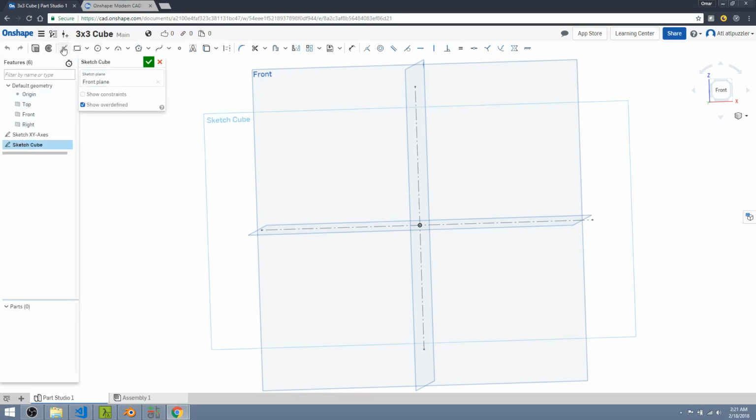Double click on it, and I'm going to choose the rectangle icon here. There's two ways you can draw a rectangle: by corners or by center, and it doesn't matter, either work. In this case, I'm just going to use the center, and hover over the center until the icon looks like this icon here. This basically ensures that the center of your rectangle is the center of the design itself. And just single click and drag and just draw whatever, and single click again, and we have a rectangle. And now click escape so we can stop drawing rectangles.